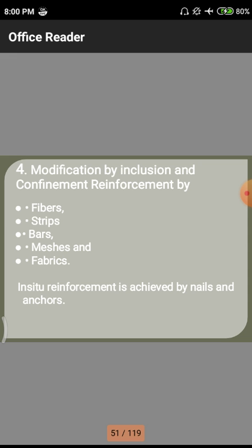Likewise, these strips are also used in ground improvement techniques. In beams and columns we have shear and buckling forces, and likewise these also occur in soils. So to prevent those kinds of stresses in the soils, we need to use strip-like materials.